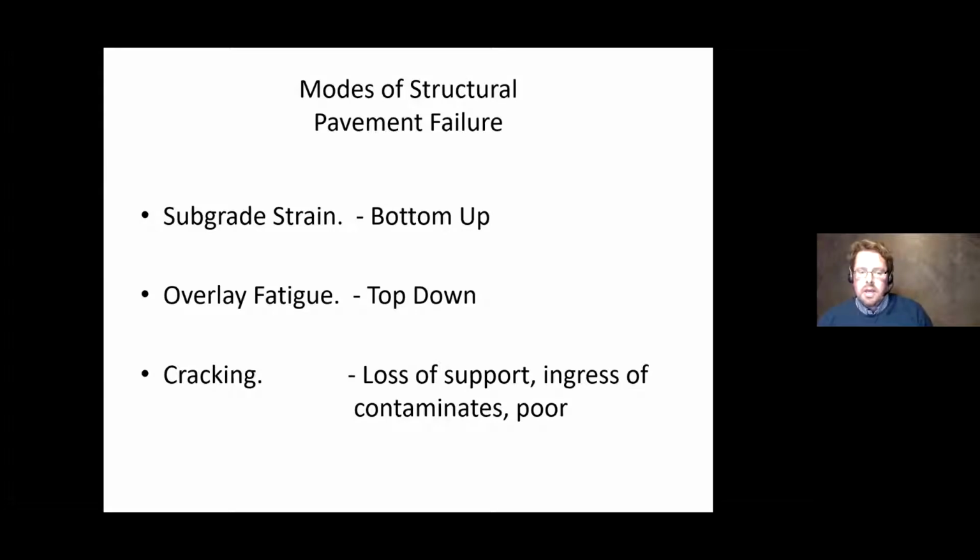Then overlay fatigue, which effectively is top down, is generally driven by just the age and wear of the overlay, or else an inadequate total bituminous thickness. So you'll start seeing the settlement again of the pavement, but it won't be as direct as a rut. You'll start seeing differential settlement and cracking. Of course, then raveling is one of the most critical examples of this. It's not exactly structural, but it'll tell you that your pavement is aged and oxidized.